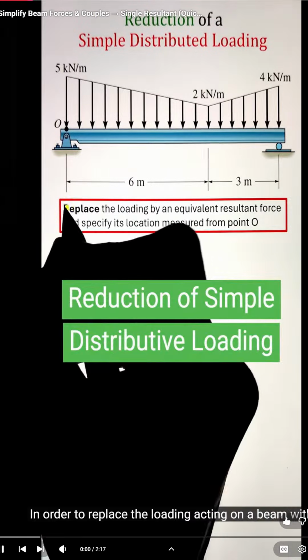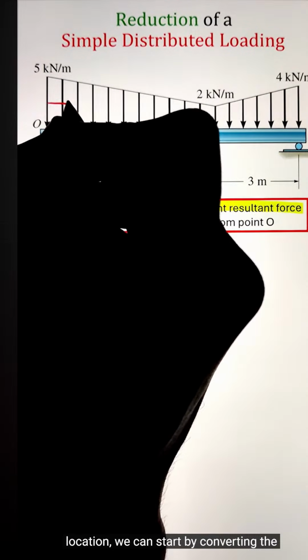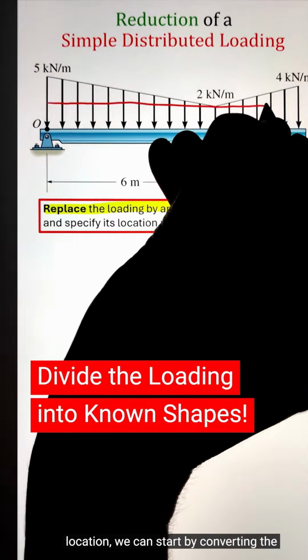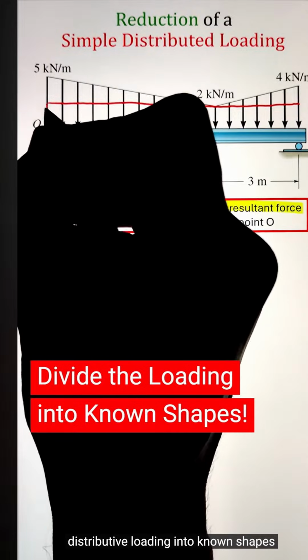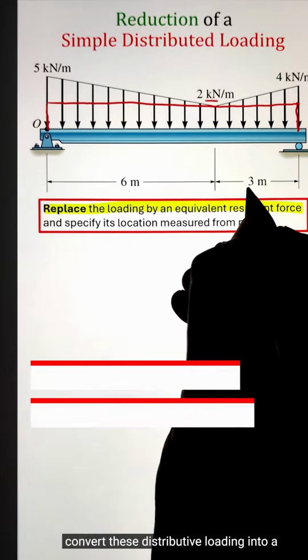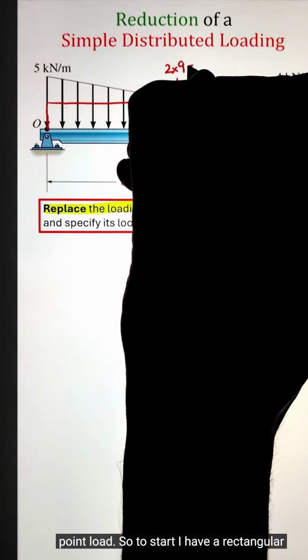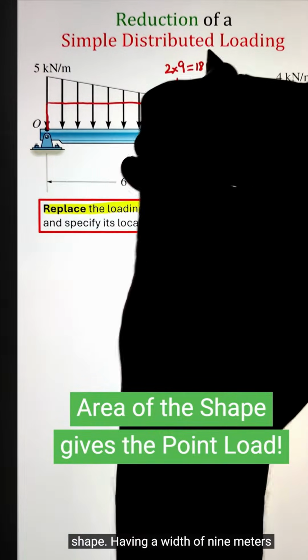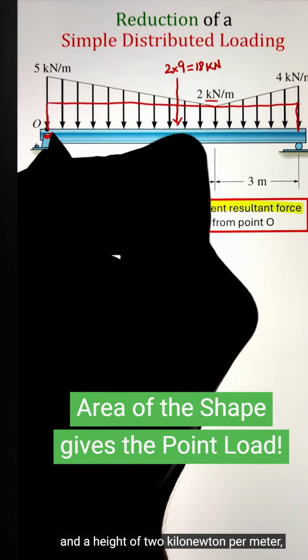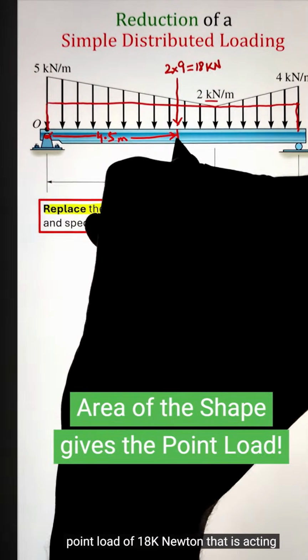In order to replace the loading acting on a beam with an equivalent resultant force and specify its location, we can start by converting the distributive loading into known shapes and then calculating the areas of these shapes. These areas basically convert these distributive loading into a point load. So to start, I have a rectangular shape having a width of 9 meters and a height of 2 kilonewton per meter. Multiplying the two will give us a point load of 18 kilonewton that is acting in the middle of the rectangle.